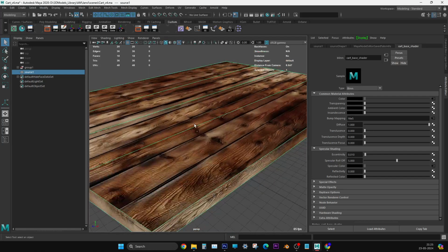So how did you do the color texture mapping? You did the unwrapping for the object, and then took a UV snapshot and took it to Photoshop. There, from Google or something, you pasted the file on the UV map in Photoshop, and then you brought it back to Maya and applied it in the color field, in the blend shader.